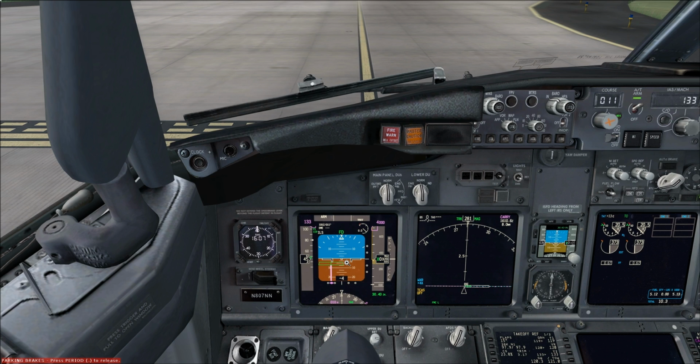Now you as a pilot can also see windshear before waiting for the system. Let's say for example the system doesn't detect any windshear, then you as a pilot have some parameters to go by to see if you're encountering windshear.